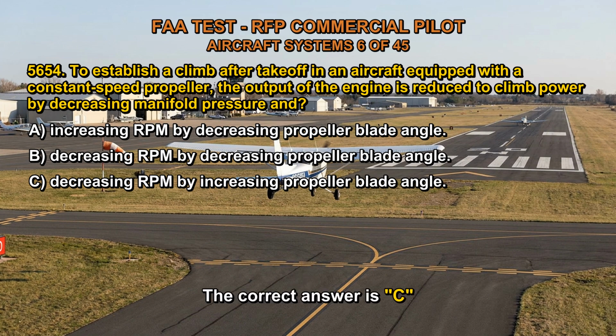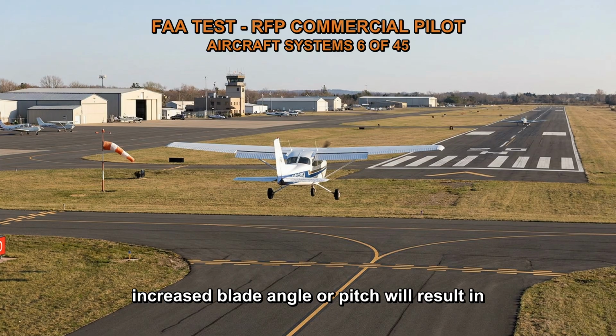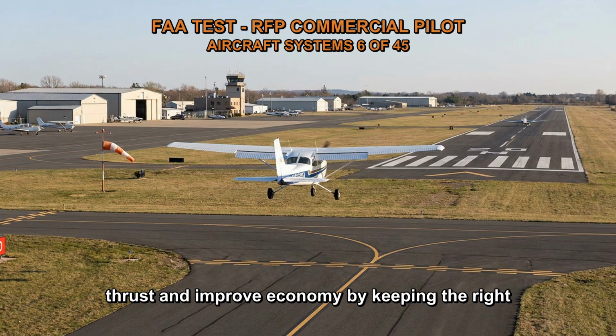The correct answer is C. To get the most power for takeoff, a low-pitch, high RPM setup is used. Once the aircraft is in the air, an increased blade angle or pitch will result in a decrease in RPM, which will produce enough thrust and improve economy by keeping the right velocity.